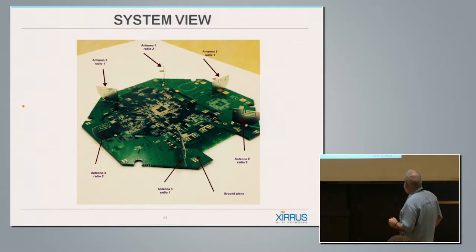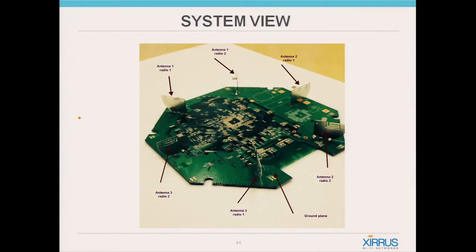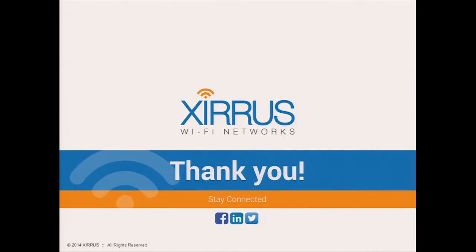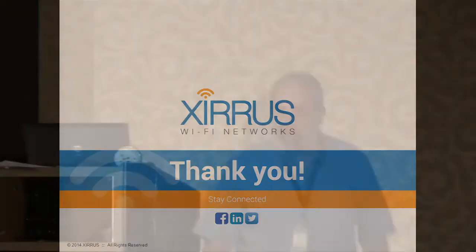At the same time, creating that kind of an arrangement helped me to achieve really nice, clean OMNI coverage, and with very minimal interference or any distortion. And the PCB itself is used as the ground plane, and gain-wise, I'm able to achieve gains in the 4 dB range, and this is a relatively low-profile access point, so it's kind of nice. Works really well. So this is kind of the end. I could talk about antennas for hours and hours.